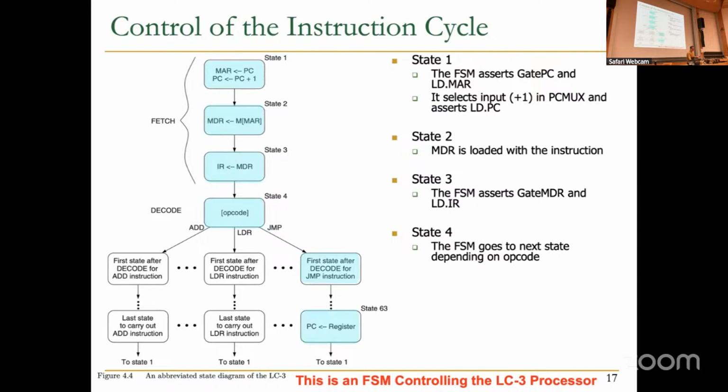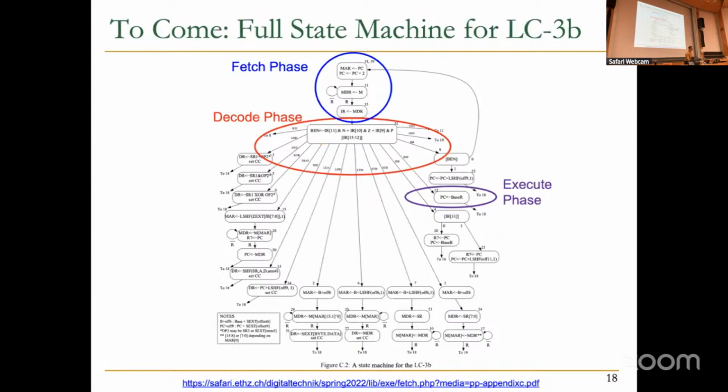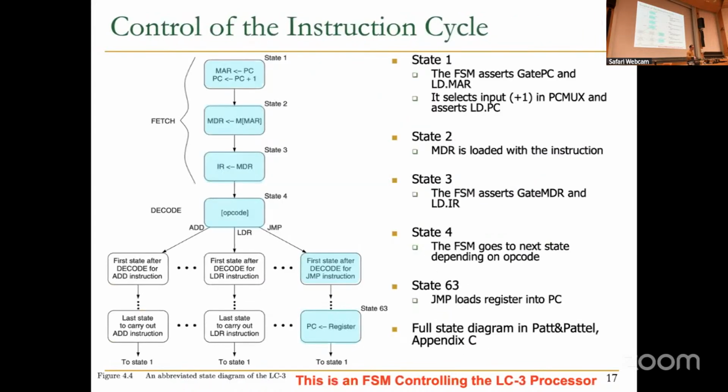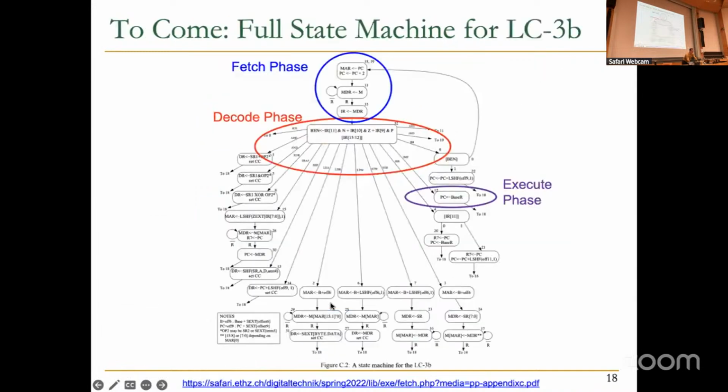There's no magic involved. This is all based on everything that we have learned in the digital design part of the course, and now a little bit of the microarchitecture part of the course. It's a finite state machine. And the full state diagram is here, essentially. This is actually the real diagram. The previous one was kind of like a toy diagram to illustrate the decode phase. You don't really need this particular state, actually. You can jump directly into a state where you update the PC with the register, as I will show you right now. So these are the 3 fetch states.